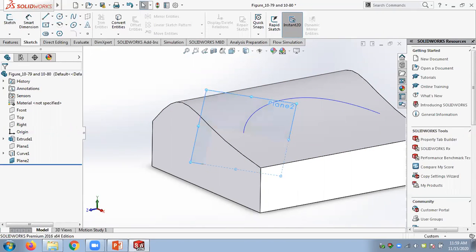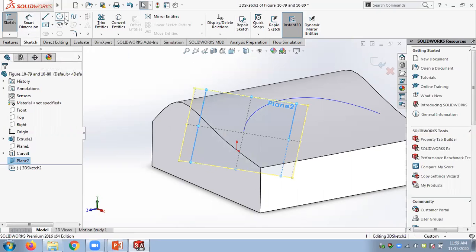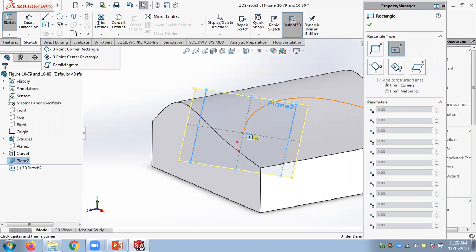So we have to select this plane, and after I select the plane, I have to go and enable this tool, not the 3D sketch. There's another tool called 3D sketch on plane. So if you just come here and enable 3D sketch, it's not selecting this plane. So you have to select the plane and come here and enable 3D sketch on plane. So that's going to work now. So then we can draw our shape here. Now the snapping is working. Coincident symbol like this.